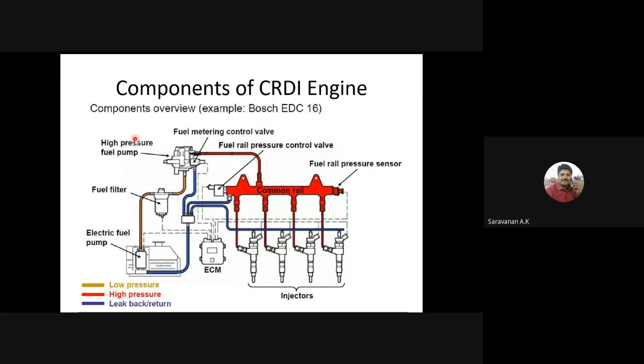Then the high pressure fuel pump is run separately by the electrical circuit, and this pump produces the fuel pressure required for the high pressure injector. The high pressure injector provides the ideal mixing of the fuel and air, directly into the combustion chamber, through the injector.